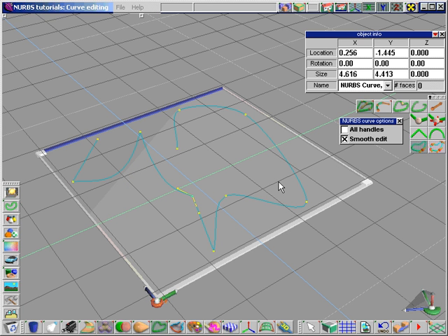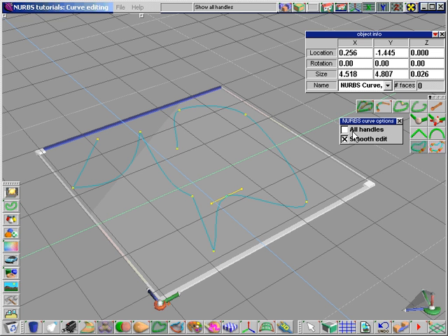Right-clicking any polygon tool brings up the NURBS Curves options, including the ability to show all the handles of a curve at once. Very useful should you find yourself with a point that refuses to move, because it's likely that the cause is a control handle bumping into the edge of its draw panel.